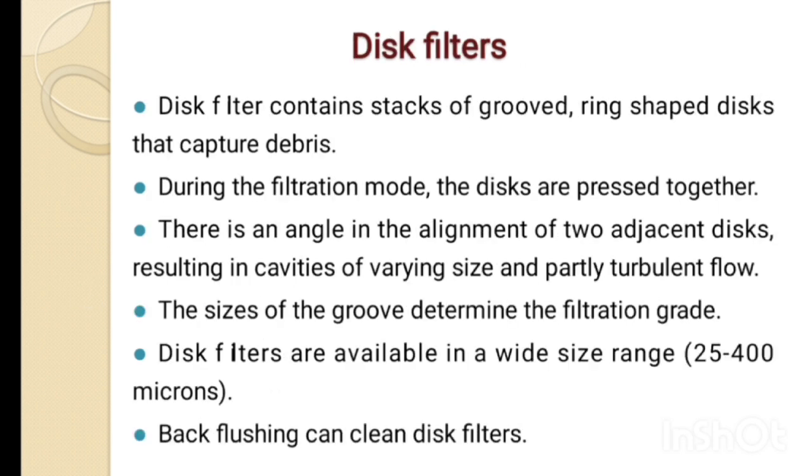Then disc filters. Disc filters contain stacks of grooved ring-shaped discs that capture debris. During filtration mode, the discs are pressed together. There is an angle of alignment between two adjacent discs, resulting in cavities of varying sizes and partly turbulent flow. The size of the grooves determines the filtration grade. Usually, disc filters are available in wide ranges of sizes from 25 to 45 microns. It can be cleaned by back flushing the discs.